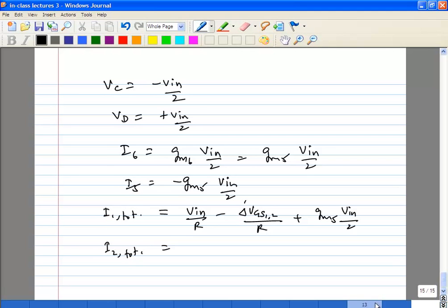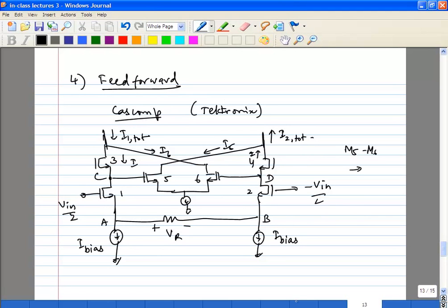Because the gain of these two guys, so input to C, the gain from input to C is approximately -1, because the input impedance is approximately 1 over GM of this guy. I'm assuming all sizes are matched right now. Almost. These two sizes, 1, 2, 3, 4, are all matched. And 5 and 6, you're going to size them based on how you want your error. So that's what I'm getting to here.